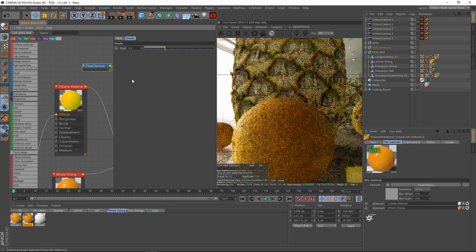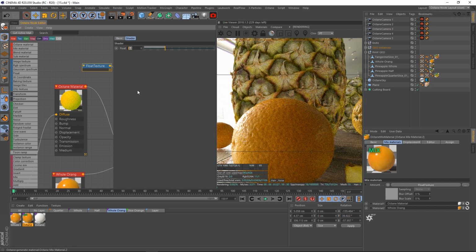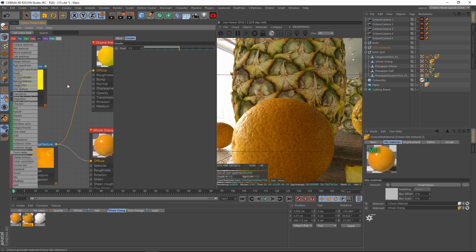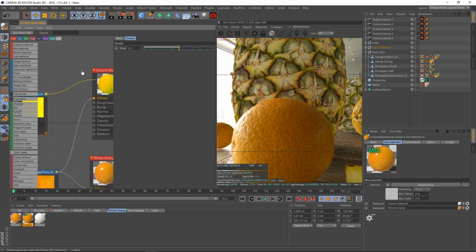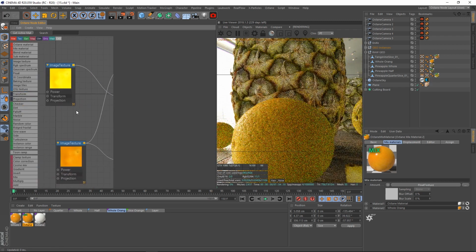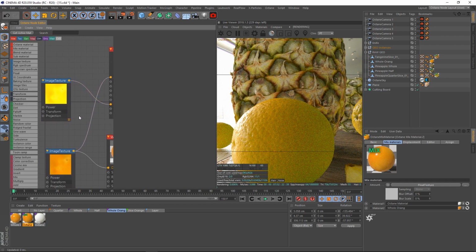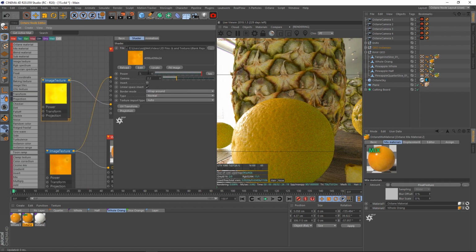So we'll drop this to 0.3. And we'll add a little bit more reflections back, maybe 0.5, something there. I forget what the default was, but that'll work. And then let's go ahead and add our subsurface scattering back into transmission. My subsurface scattering is simply a copy of the default blank repository orange color map, just the default diffuse map. I copied it and then upped the power to 3.